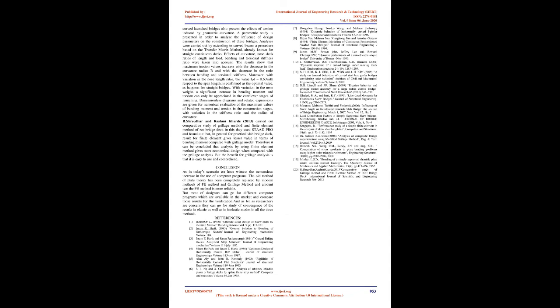R. Sridhar and Rashmi Kard, 2013, carried out a comparative study of the Grillage Method and Finite Element Method for an RCC bridge deck. In this they used STAAD Pro and found out that, in general, for a practical slab bridge deck, the result for finite element gives a lesser value in terms of bending moment compared with the grillage model. Therefore it can be concluded that analysis using the finite element method gives a more economical design when compared with the grillage analysis. But the benefit of grillage analysis is that it is easy to use and comprehend.